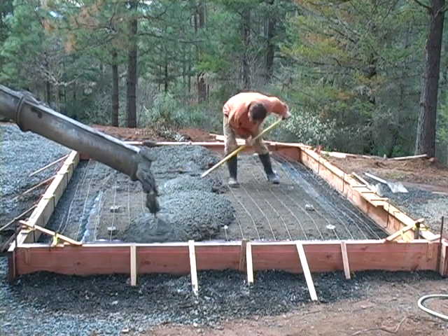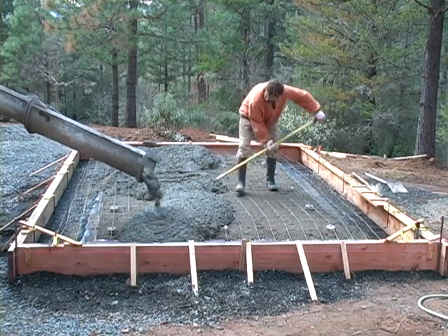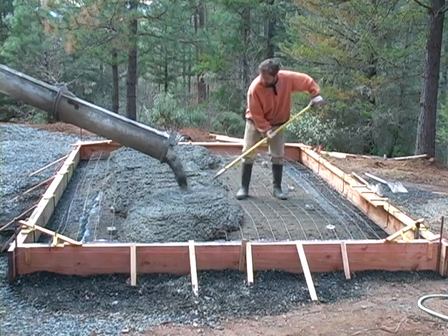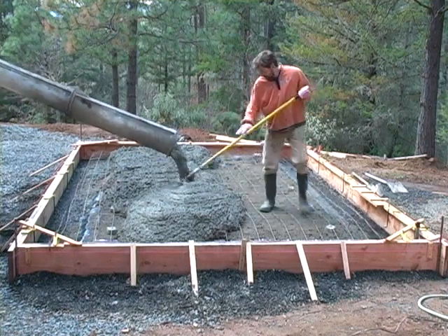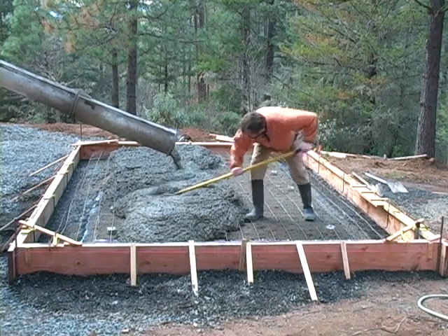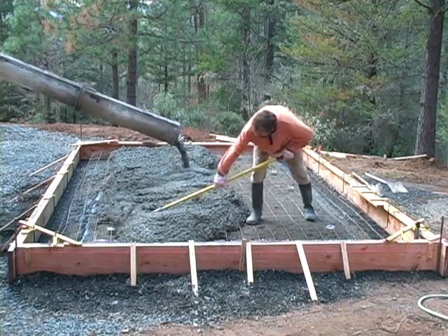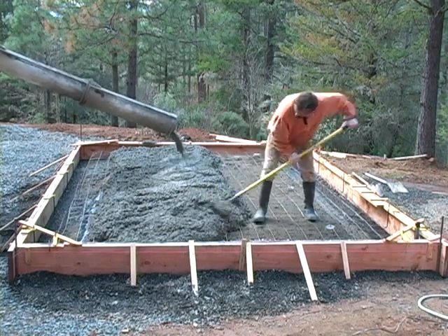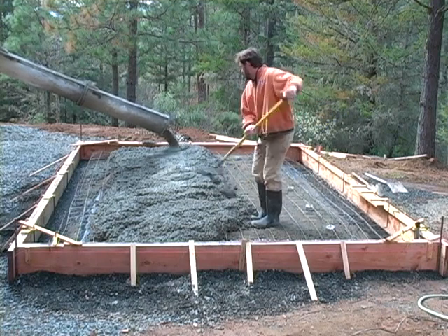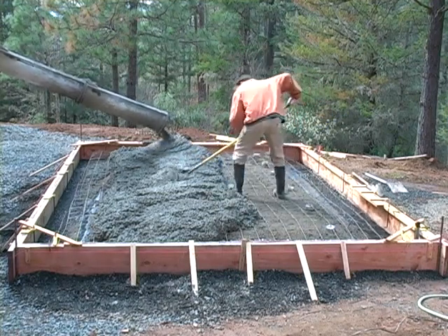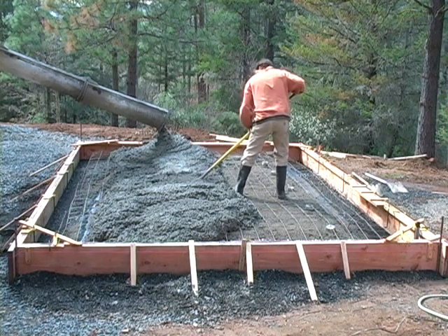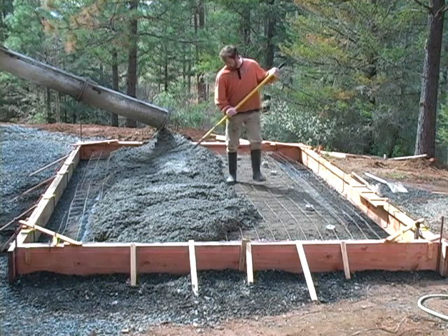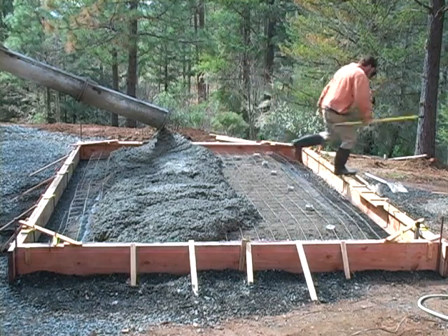Another thing you may notice is that he's dumping the concrete pretty much right in the middle of the foundation slab forms here. Because of the terrain, we weren't able to get the truck right up onto the forms. Now, if you can avoid this, do so at any cost, because what it means is I'm going to have to move this concrete to all the corners of the slab without the help of the chute. Not only is this laborious and tiring, but if I'm not careful, I get some separation between the aggregate, or the larger pieces of gravel in the concrete, and the rest of the mix. Now, if I get separation, that's going to create a problem of uneven curing throughout the rest of the process.